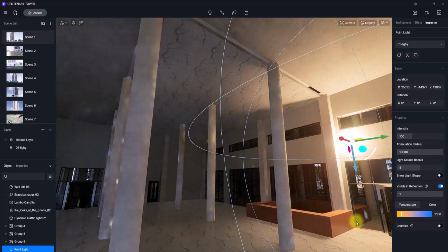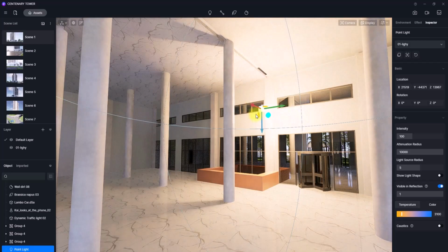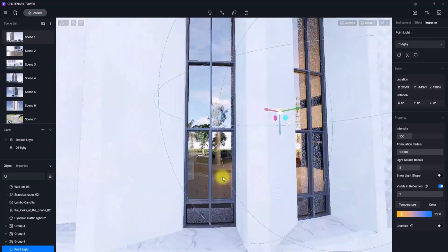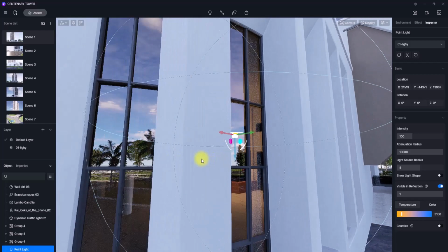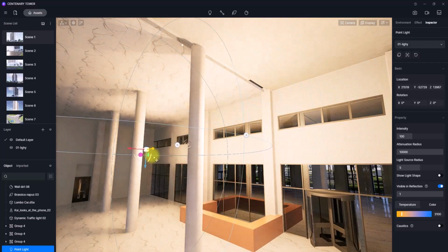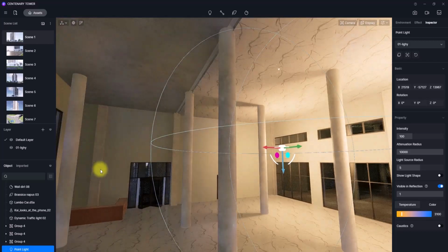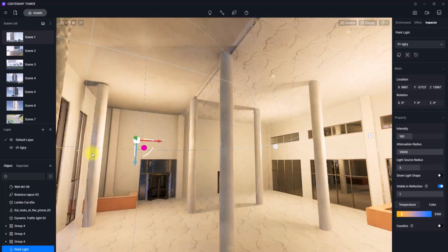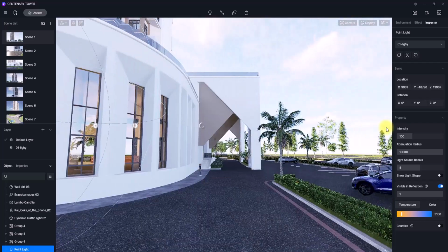So what happens is that if you are placing light in D5, you are actually going to place it on a parallel or perpendicular wall to the opening. I just spoke some mathematics grammar. What it simply means is that this light is placed on this wall, it's reflecting on the surface of this wall and coming out through this window. If I copy it, you are going to see how the light will simultaneously increase and its efficiency will increase more. So we're just going to do this for the ground floor spaces, these lower floor spaces, and just illuminate the interiors of these spaces.